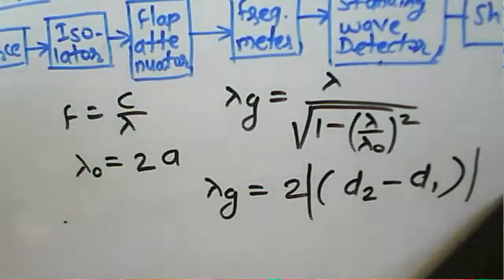So that's all about the measurement of frequency. We have seen today the measurement of power and the measurement of attenuation. For attenuation, we considered the RF substitution method and another method, the power ratio method. In the power ratio method, we measure the power with the device under test and without the device under test.